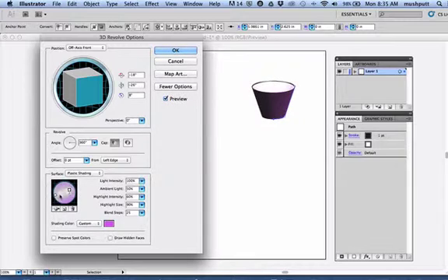Okay. You can also adjust, of course, the intensity, the ambient light, the highlight intensity, the highlight size, blend shape. That's how many steps it takes to get from your lights to darks. So let's just explore here. Sometimes it can make a much smoother transition of color from your lights to dark, and sometimes it can start to look choppy. So you should explore that as well.